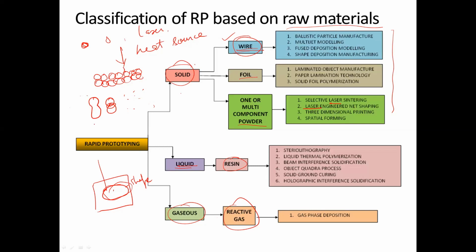So localized binding will take place. When the heat moves through, not only this particle is getting deformed, but also this particle, and heat also penetrates inside. So the third particle, which is over here, also gets some heat through the system, and as a result these three particles may bind together. The structure of the bound particles will be something like this, which shows that a complete homogeneous bonding has taken place. So this is how powder particles work.